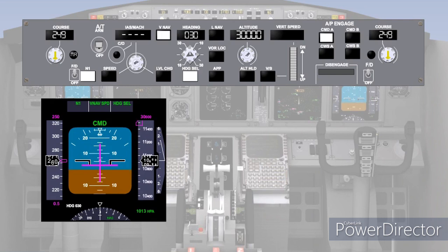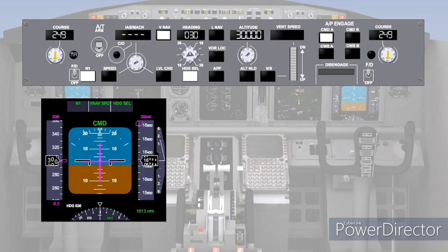As the aircraft climbs, the speed transition is automatically commanded at 10,000 feet, and an automatic changeover from speed to Mach occurs at the required point. As the aircraft approaches 30,000 feet, the aircraft will carry out the altitude acquire maneuver, but this time it is not annunciated. Instead, the pitch window will change to VNAV path, and the autothrottle will change back to speed. The pitch channel of the autopilot is now maintaining the altitude or vertical path derived from the flight management system.